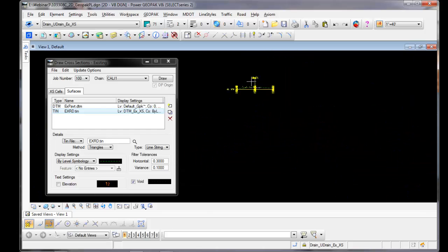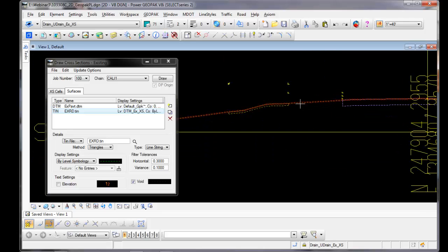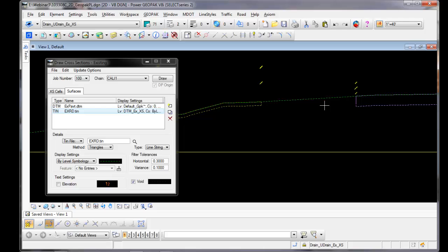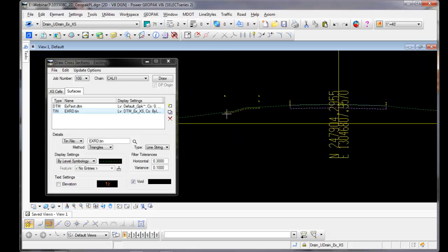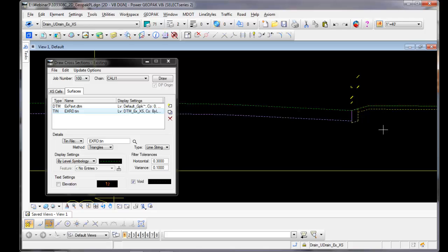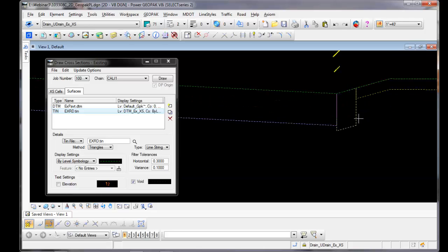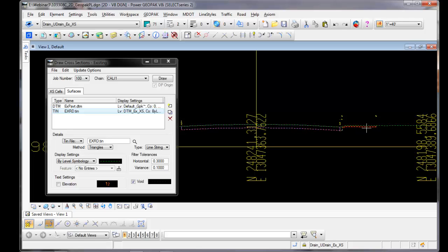But you can see here that this is an area where there's an aggregate shoulder, so there was no component drawn there. And then of course I have my topsoil stripping section. It draws the pavement where I have different sections. Here's a section that has the curb and gutter line, or that curb line in it, so you can see that it does draw the curb and the topsoil stripping after it. Those tend to draw the topsoil very well when you have that.